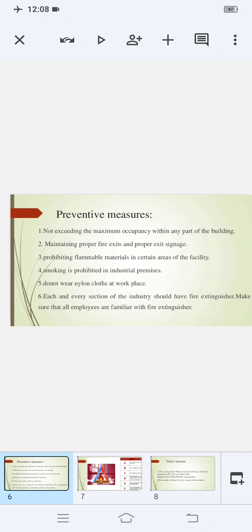Fire resistant brick walls or reinforced concrete walls can limit the effects of any explosion. The roof should be designed to lift easily under an explosive force. Possible sources of fire are reduced by eliminating unnecessary ignition sources such as flames, sparks, heated material, matches, smoking, welding, cutting, and static electricity. First of all, we should check the building construction. It should be constructed in such a way that fire cannot spread from one building to another.